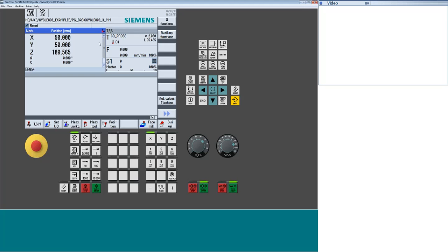Now, as I want to move the machine around, I can start to move it manually. So manually, I'm going to crank down my override. I can pick my axis definer. So here I have a 4th and 5th axis buttons. This may look different on the machine tool you're on, but once I select them, I can jog those axes. So if you notice, when I pick my 4th, my A starts to physically move. As well, if I pick my 5th, I start to see my C or my platter is spinning.